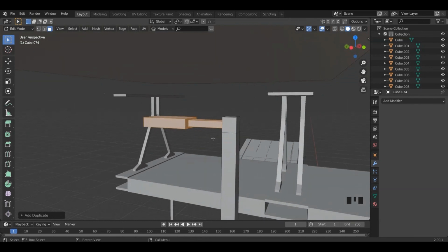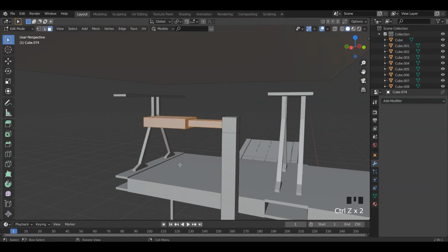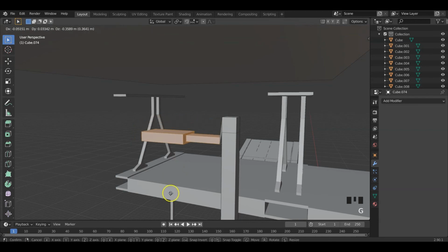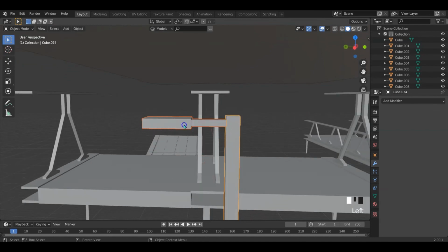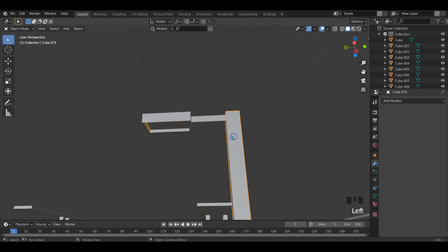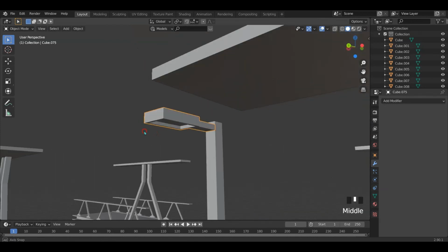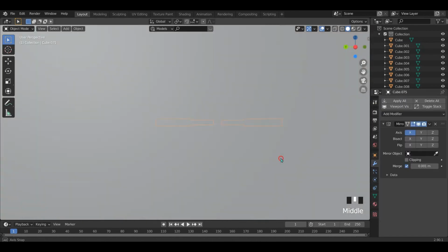What I'm planning is I'm going to select these faces, and now I'm going to separate them and make it into a separate object. Just double checking whether I haven't by mistake duplicated anything. Oh, you see I missed out one face. I'm going to separate this and I'm going to join these two together so it becomes one object. Now I'm going to mirror it with the reference to the pole, and it's mirrored. Perfect.